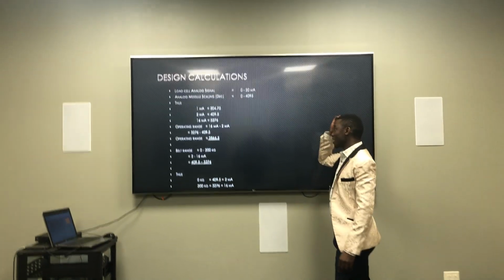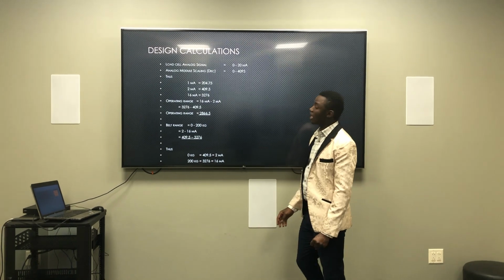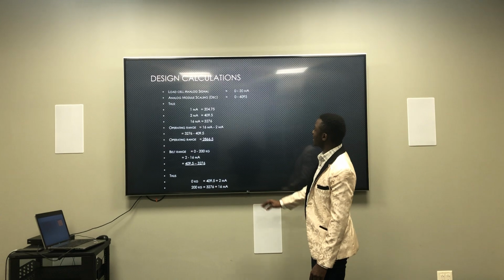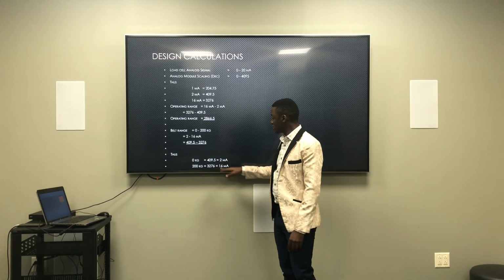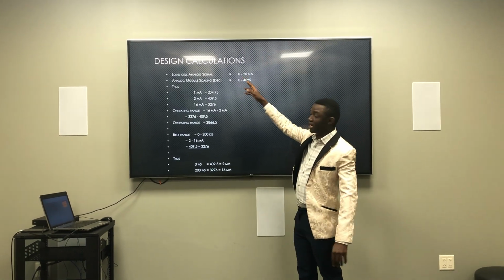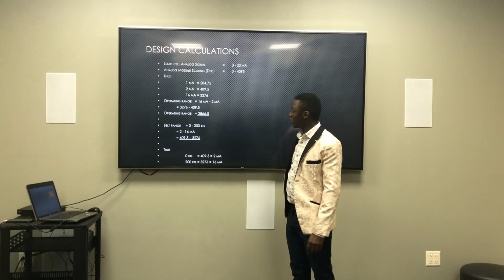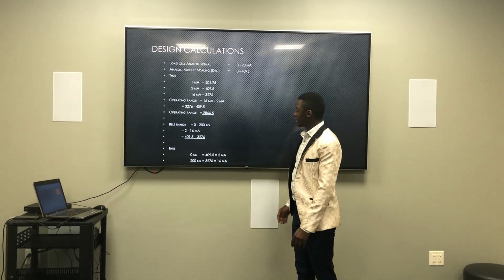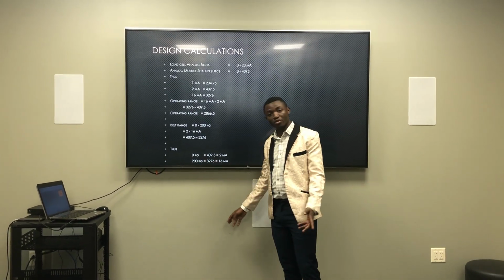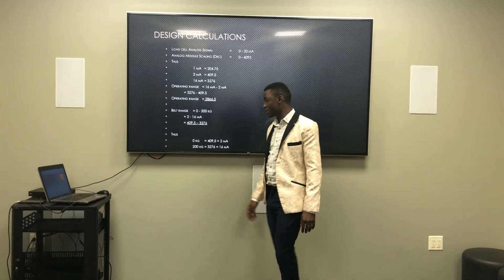I also have design calculations, which are basically calibrating our weightometer to the PLC. We want to have a range of 2 milliamps to 16 milliamps instead of 0 to 20 milliamps, so that when we get a 0 reading on our weightometer, we know that there is an error, and the maximum we can get is 200 kgs on that weightometer. We got that value from the data sheets on the weightometer.